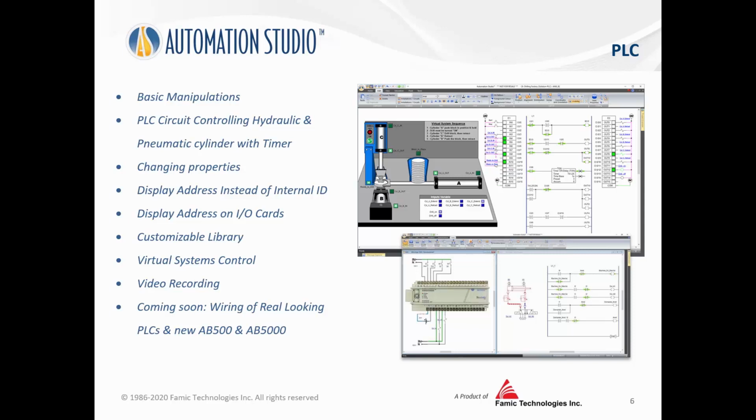We will put a timer also in that circuit. We'll change properties on some of the components. We'll also show you how to display the addresses instead of displaying tag names in Automation Studio. We'll show you how to also display the addresses on the input card.